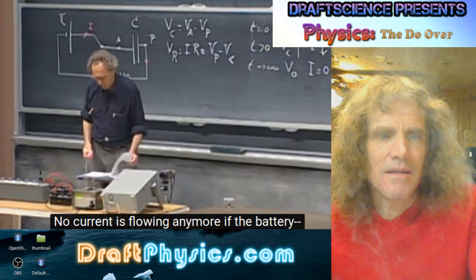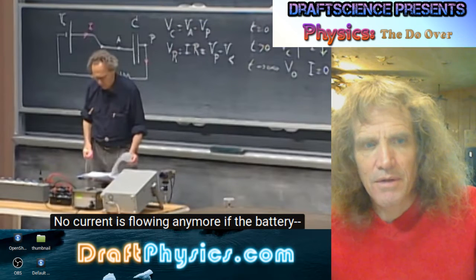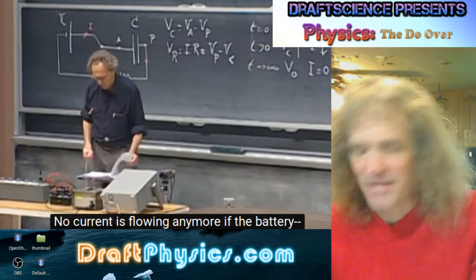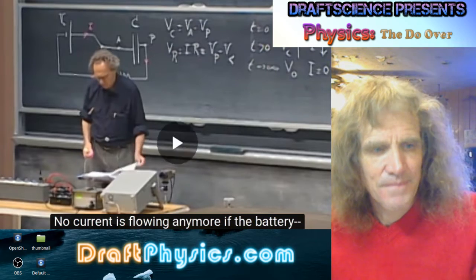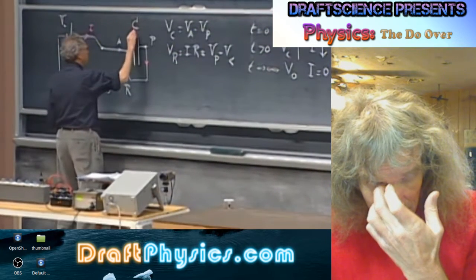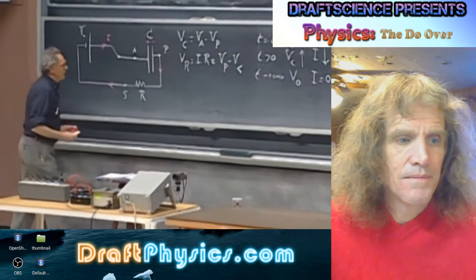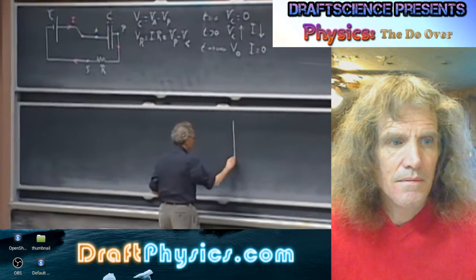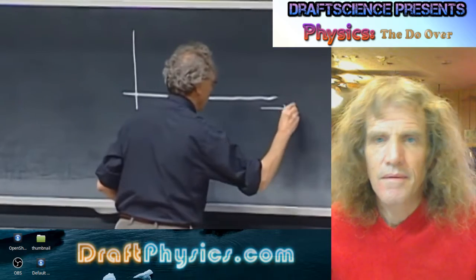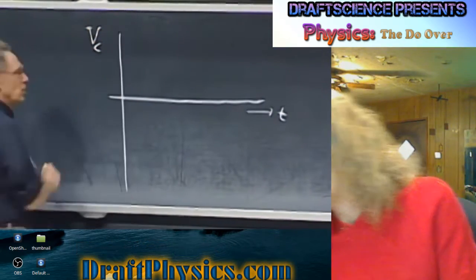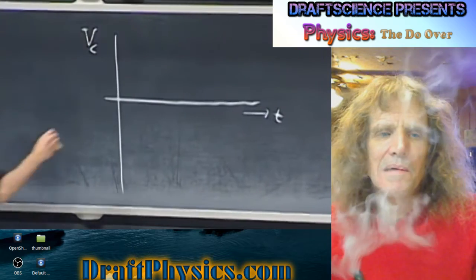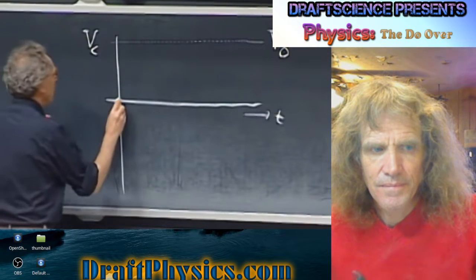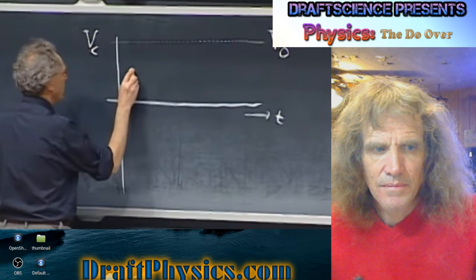It's not a very good diagram, right? 0, down, 0. It has to go up first before it can go down. This capacitor is going to charge up, this becomes positive, and this becomes negative. And so you can construct a plot whereby you plot as a function of time the potential over the capacitor. We haven't used any differential equations yet. You know that if you wait long enough, you will reach that value V0, and it's going to build up like this, asymptotically reaching that value.